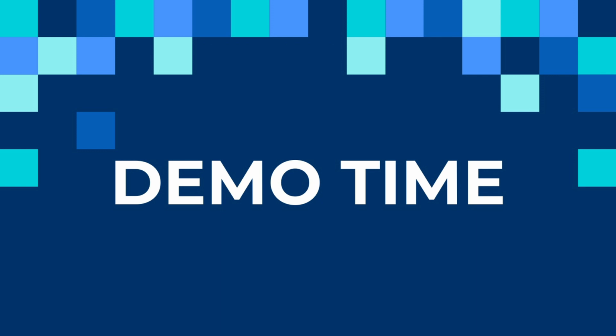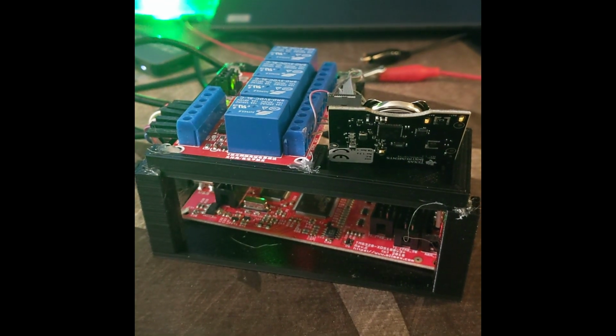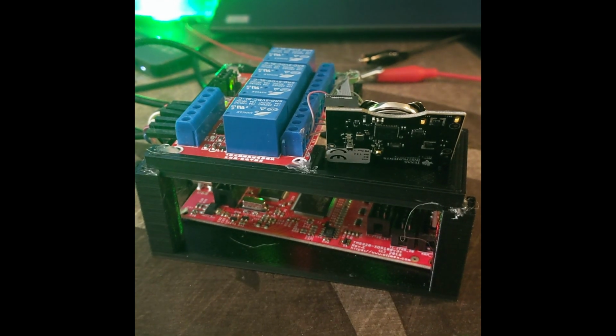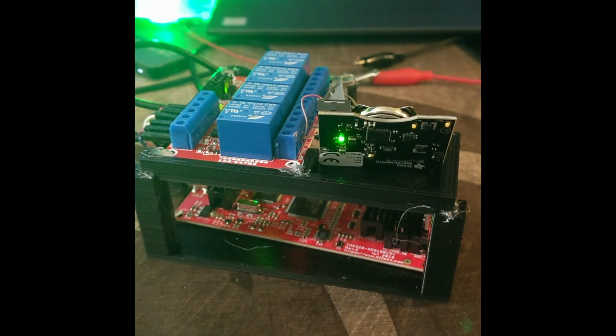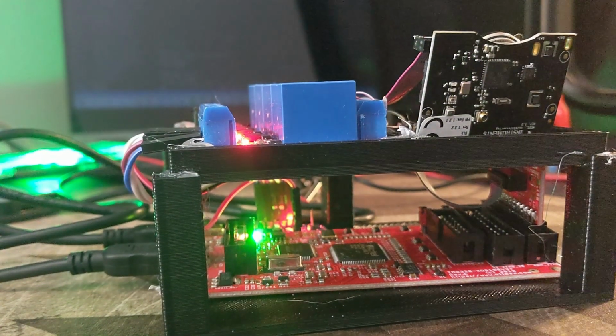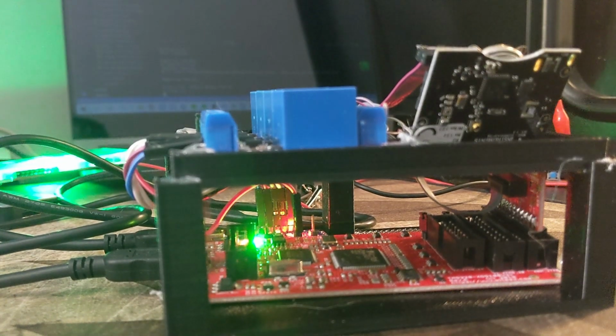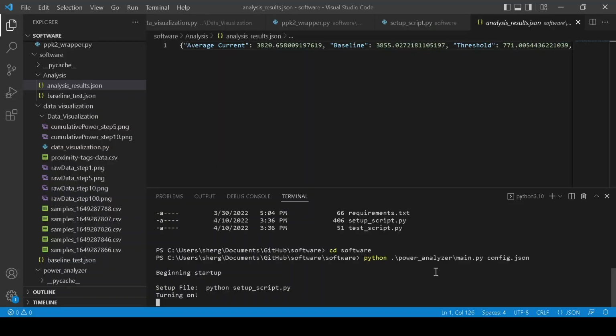Say that I am a developer at Triax Technologies looking to analyze the energy consumption of my Texas Instruments CC2650 sensor tag. We want to test a new firmware that blinks an LED many times upon launch to gain the attention of the user. I connect my power profiling kit and JTAG and get ready to run my Python script. I locate the script main.py and call it from the terminal command line with our configuration JSON file that contains the firmware, test script, and analysis script.